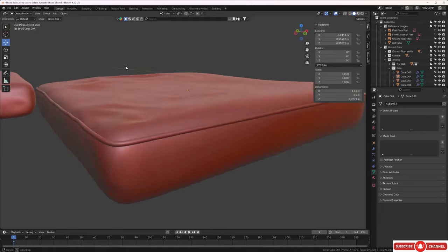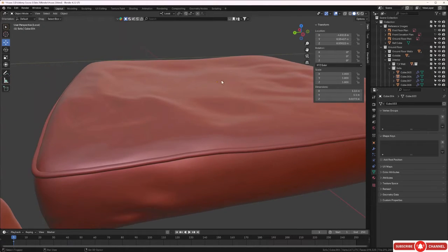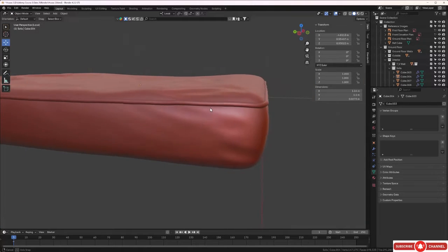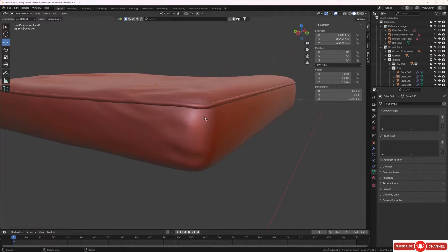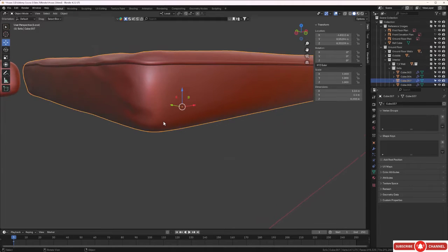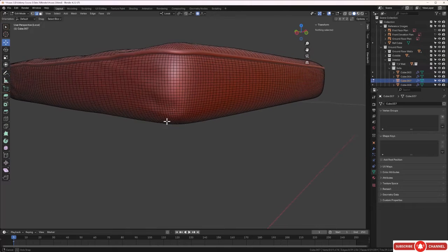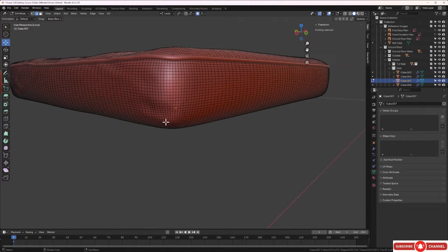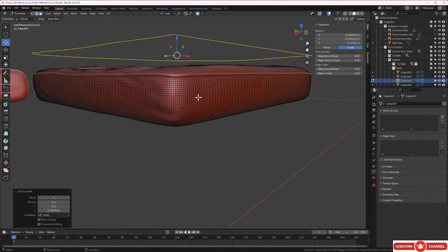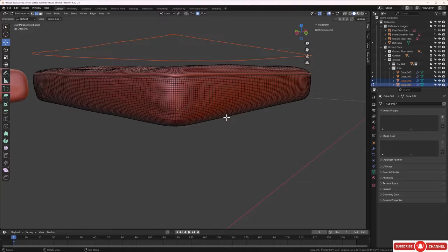Now let's go ahead and pull this down until it's back where it was, and just have a look at it and see if it's actually sitting in the right place and see that it looks good. And I like that just where it is. Yeah, that looks good. So I'm going to do the same now for the bottom edge here. So I'm going to tap into edit mode again, and I'm going to hold Alt and I'm going to select a loop, and I'll select it about there. I'll press Shift D and Z and bring it up, and I'll press P and I'll separate by selection.